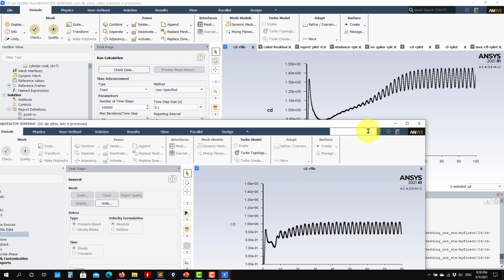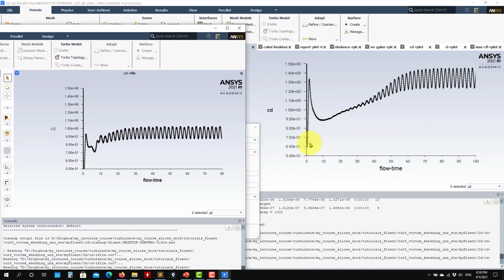By just adding that perturbation, see that the initial transient, where you need to run the solution for like 70 seconds up to the point that you can say that maybe here you have something that is statistically periodic, now it starts to become periodic. Instead here, very fast, already in 30 seconds, you can start to take statistics. So these are tricks, techniques that you can use to speed up the convergence.